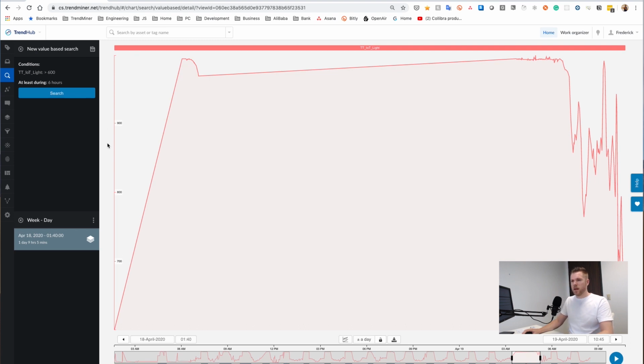However, you can anticipate that this behavior would also happen when your light sensor would be offline, or it would be maybe in error state, or would cause some consistently high readings. So having those outliers can be a trigger for me to actually check the health of my sensor as well.